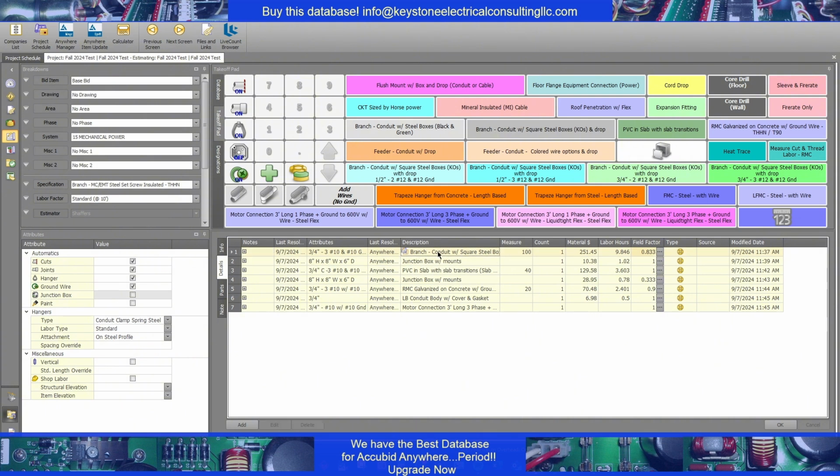I like that. We've got our EMT, our inside junction box, PVC, outside junction box, our rigid over to the disconnect, and our motor connection. One thing I don't do, here's one thing that I'm going to stop just technique-wise and say, am I going to put the disconnect in here? No. And here's why. Typically because I count the disconnects off of a mechanical schedule, usually.